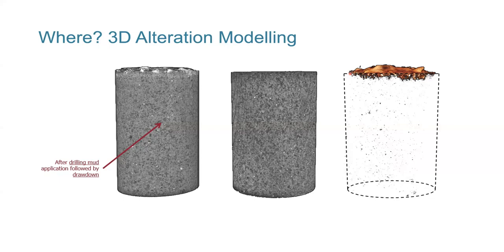So we can see the external mud cake hasn't cleaned up properly. And then we have a few millimeters into the core sample where we have significant operational fluid constituents. You can call it an internal filter cake if you want, in the first few millimeters. And then deeper into the sample, we've got lots of scattered pores where there's change. But the most important zone in this particular study is in the near-wellbore.